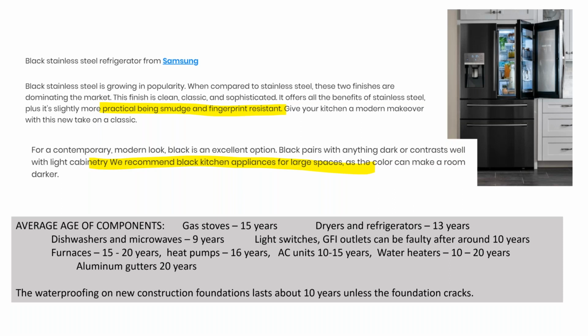They're going to die. Same with hardwired smoke detectors. They die too. So just because you have a hardwired house doesn't mean that they don't need to be switched out. If you go in and you see the battery has been removed from them, it's a sure sign that the smoke detector itself probably needs to be replaced. Furnaces can last over 20 years depending on the brand. There are a few furnace companies that actually went out of business because they always built them and they never died. Williamson was one of them. Those furnaces lasted 50, 60 years.